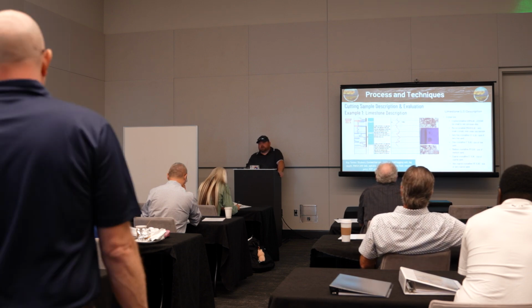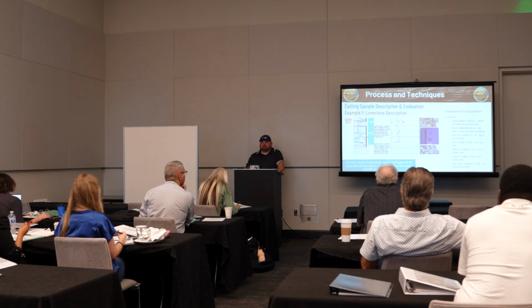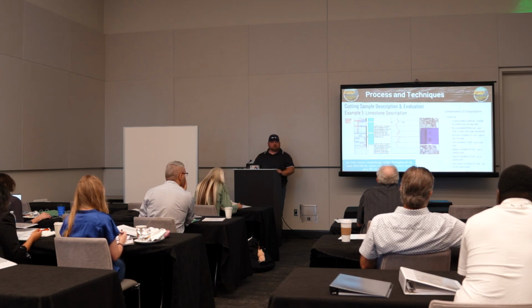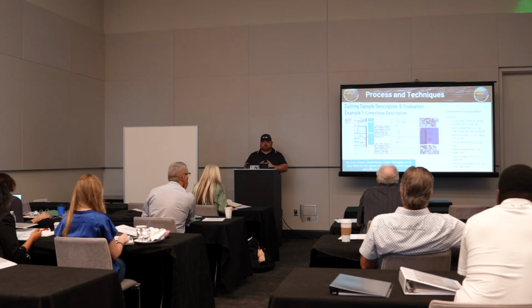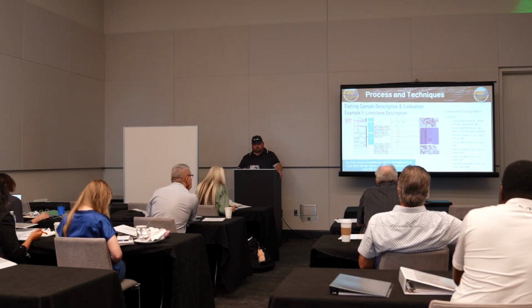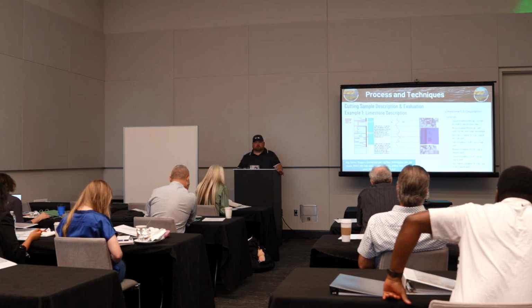Crystalline is a big one because that goes back to your hardness. The finest being cryptocrystalline. It's too small to see even with a microscope. The crystalline structure of the limestone is just so tight that you can't see any gap between it at all. Micro, very small, hard to see in a microscope, but can be seen.